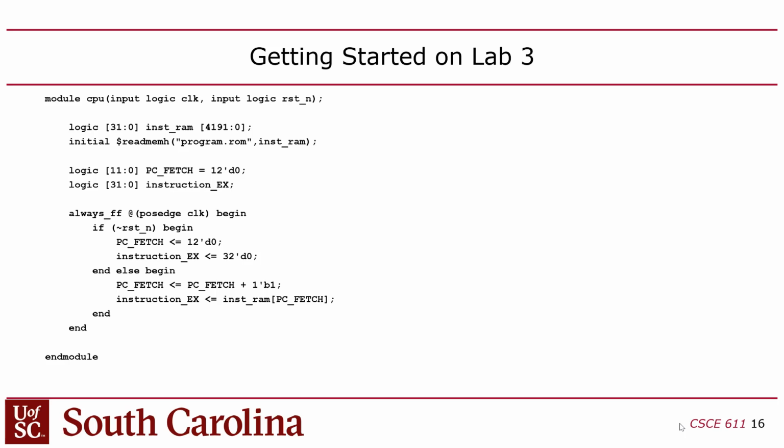So because there's no way to write a loop, we're going to take advantage of the odometer rolling back to 0 to create a natural infinite loop that the program will run in. And so what this will do is make the whole thing interactive, because anytime you flip a switch on the FPGA board, the program will instantly react because it's running in an infinite loop that only takes 4096 divided by 50 million seconds.